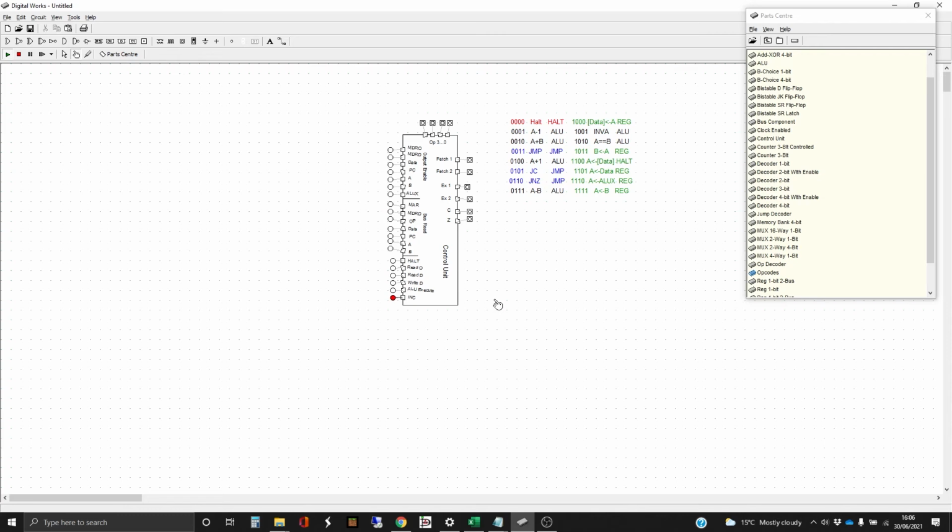So fetch 1, can we remember what it needs to do? It needs to get the program counter and put it in the memory address, and then grab the operation out of the data. So the top half is from, the middle bit is to, the thirds, and then extra stuff is the bottom. So fetch 1: program counter to memory address register, read out, read D, that's fine, and inc is set as always.